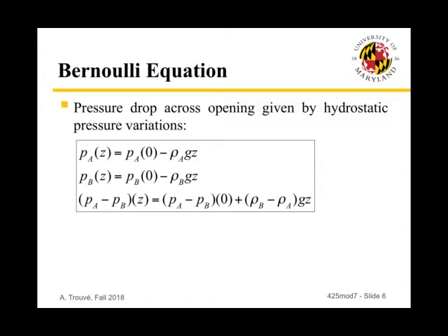And in the context of fire modeling, the mass density of the gases inside the fire room is much lower than the mass density of outside air. And this will be enough to create some pressure changes that are going to be driving the flow.